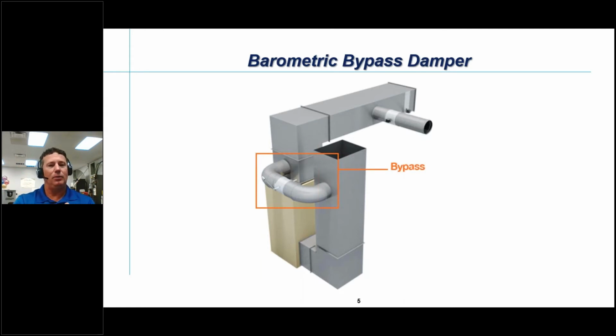And the intention of using a barometric damper is, say we got 3 zones on this house, and only one of those zones calls, and it's got 400 and some CFM on it. And on that old system, that was a PSC motor 5-ton drive. I would have probably, if I knew how to check it at that point, which I didn't understand exactly what I was looking at, I guarantee if I wouldn't have had some kind of way of bypassing air, I would have had well over 1 inch of static on that system, which puts an excessive load on that PSC motor.